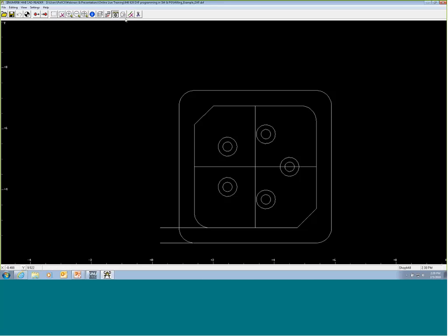So first thing, obviously, I normally do is get rid of all my dimension lines. Now, this kind of confused me when I was first getting used to this software: these little hashed or dotted line boxes that we see right here. It says select the machining range. My first gut would have been, oh, this must be a zoom. It's not actually a zoom.